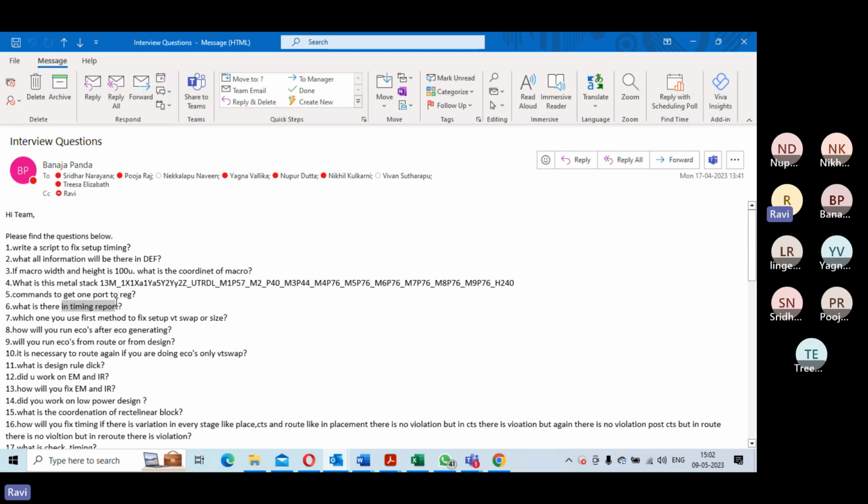If you give the option to specify the derating factor, that can also be present in your timing report. You can even get the information of the uncertainty value used, the derating, and the cell library types used. You can get all the information that is required in the timing report. You can specify these things.